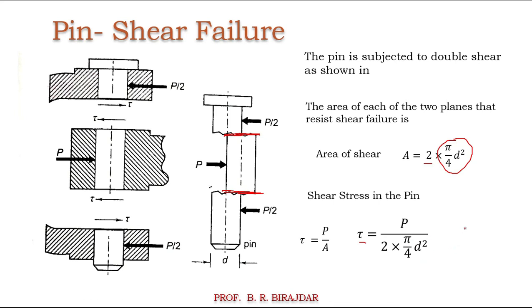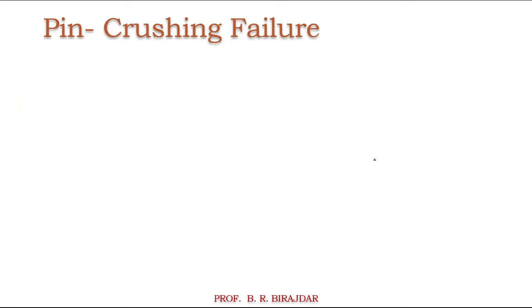Now when the pin is new, at that time only shearing may take place, but after some usage of this component, due to decay and corrosion, erosion, the component may fail due to bending also. That we will consider here. So before that, the crushing also we will see.